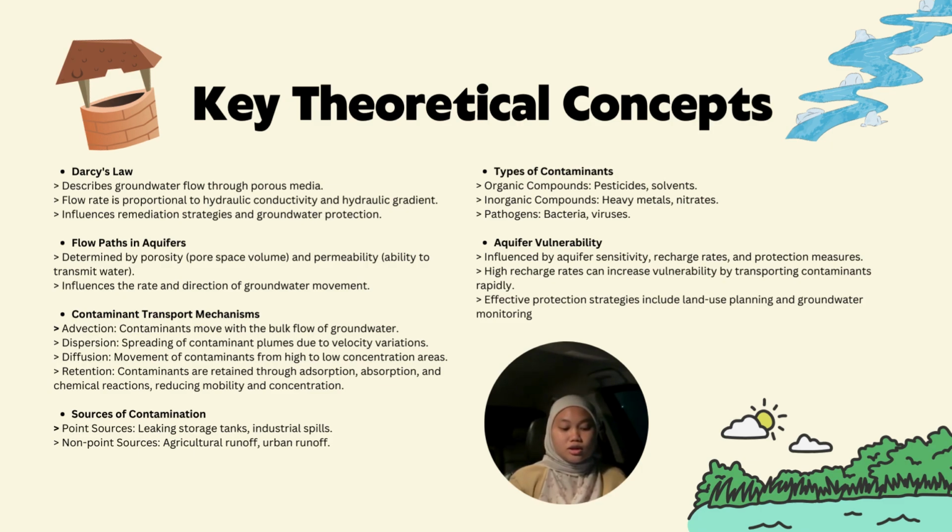Sources of contamination, which are point sources, such as leaking storage tanks and industrial spills. Non-point sources are agricultural runoff and urban runoff. Types of contaminants, which are organic compounds, such as pesticides and solvents, or inorganic compounds, such as heavy metals and nitrates. Pathogens are bacteria and viruses.